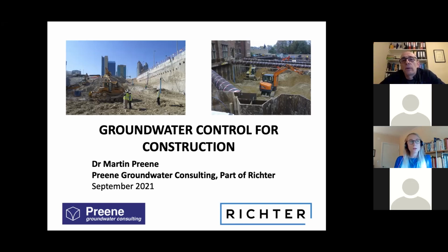Well, I think that's a really difficult question. Over the years, I've written books and guidance, and we always have a section on cost, and we've never been able to come up with a way of being able to compare different methods. Sometimes if you read a book on ground treatment, you can find it would say that there is so many euros per cubic meter of treated ground, or maybe for a diaphragm wall, it'd be so many euros per square meter of wall. Because dewatering systems are so difficult, there's no generic comparison. You would have to look at your project and cost it then.